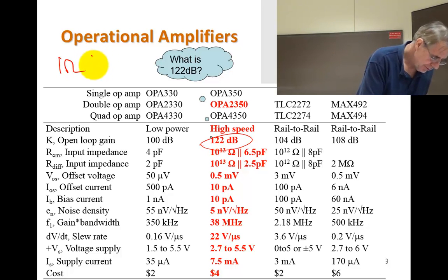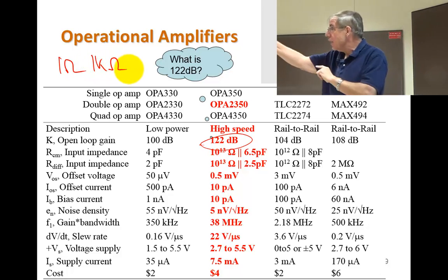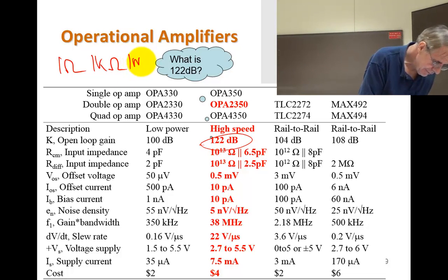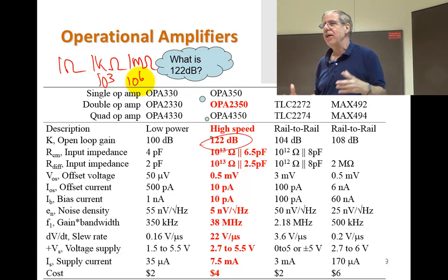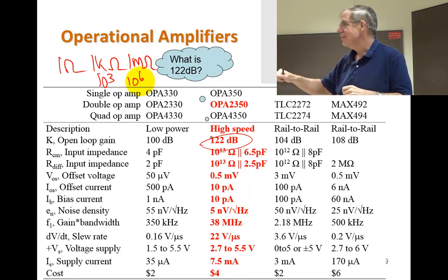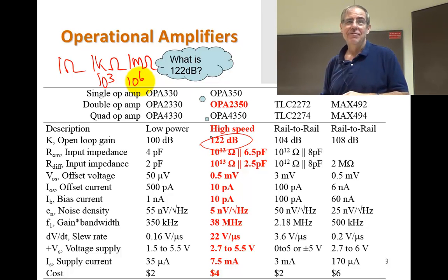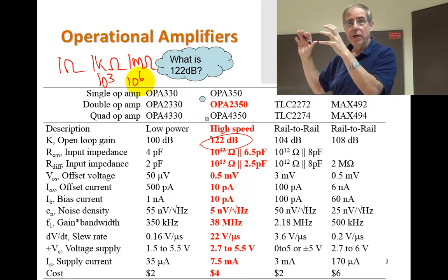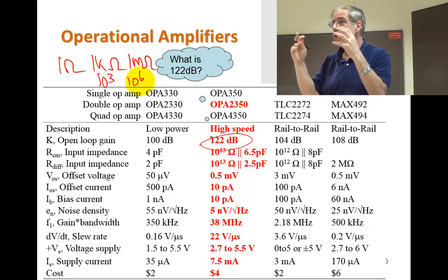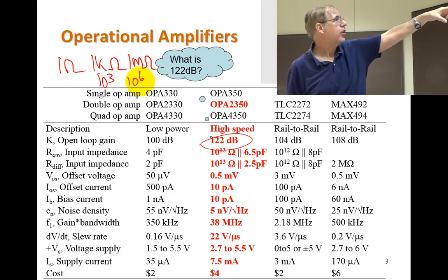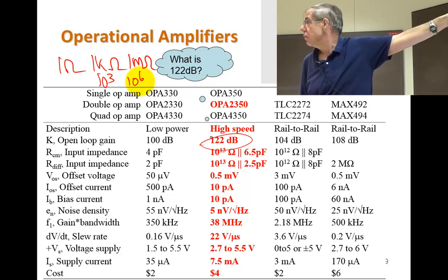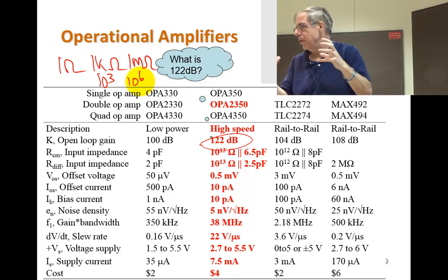Click. Kilo ohms. One more click. Megohms. Right? 1, 10 to the 3rd, 10 to the 6th. Where on your dial is 10 to the 13th, that's like 10 teraohms? No, there's no T spot on your ohm meter. Don't try to measure that. It's so large you can't really measure it. That's the essence of rule number 4, by the way. Remember rule number 4? No current in there. Well, that's because you've got to drive current into a 10 to the 13 ohm load. Just saying, it's pretty large. Can't get in there.